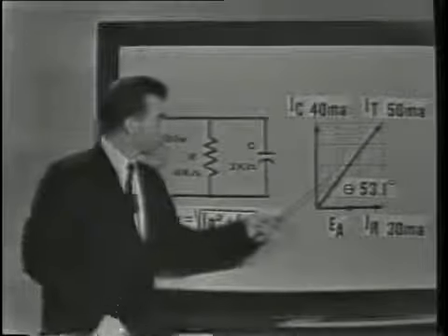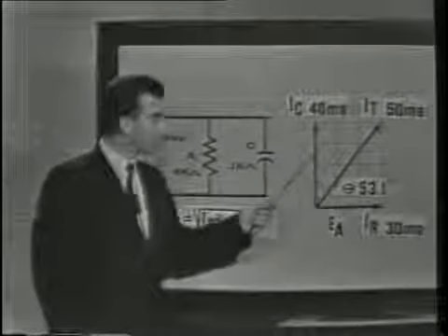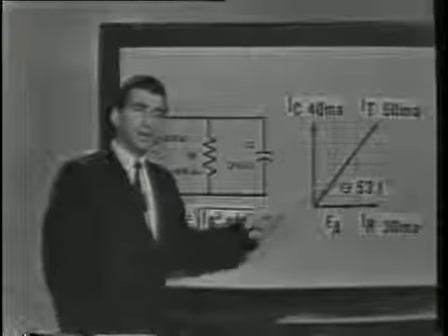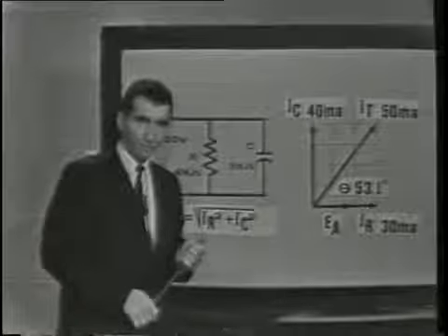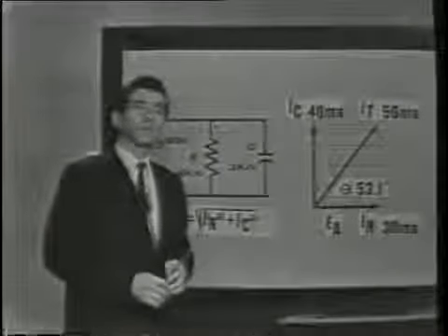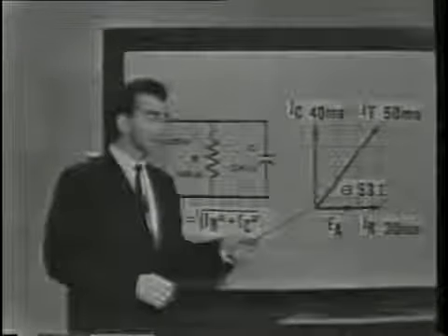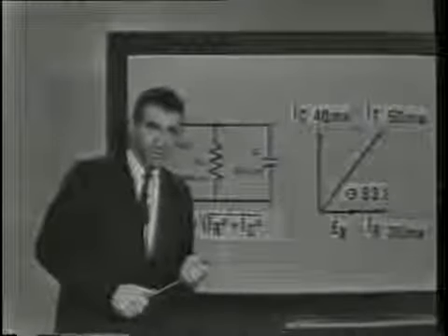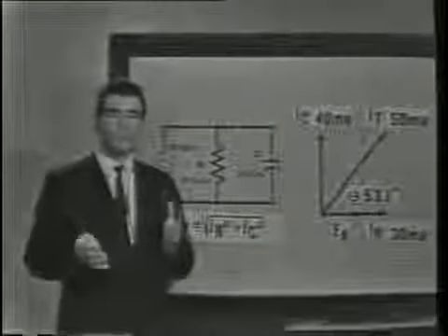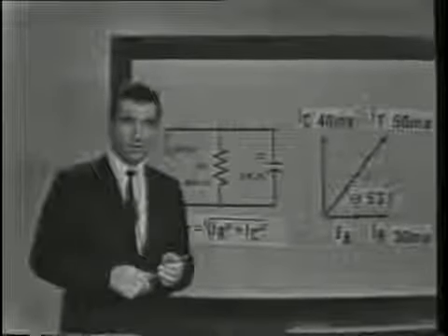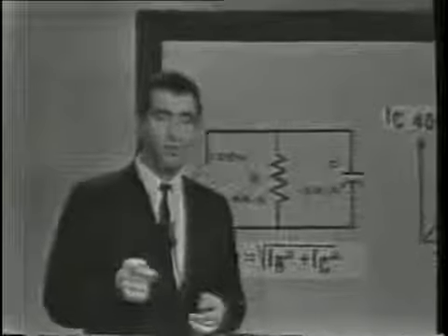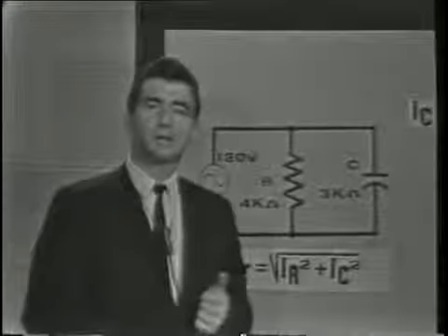And the phase angle can be determined, once again, by simply measuring the graph, or, more exactly, by calculating the sine or cosine of angle theta, or the tangent, and using the trig tables. The phase angle is important to us because it gives us an indication of the power factor, which we defined as the ratio of true power to apparent power. Now, the facts we've discussed concerning this circuit will become more important to you as you gain additional knowledge of their application, so know them well.